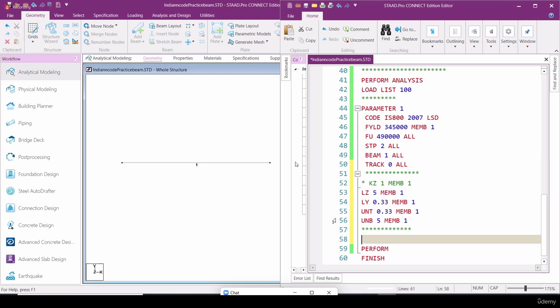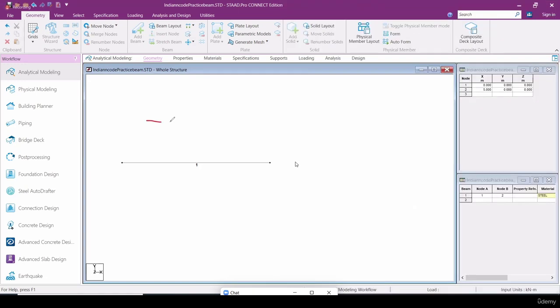It means the width of the deck sheet is 330 mm only? No, the width of the deck sheet is not 330. It is the screw spacing. I'll draw it again. The approximate tentative shape will be like this. Screws will be connected to the joist like this.